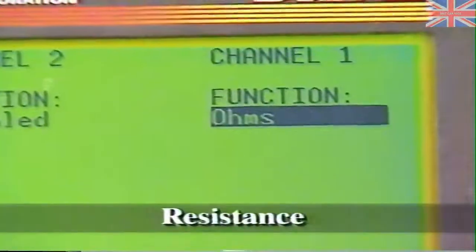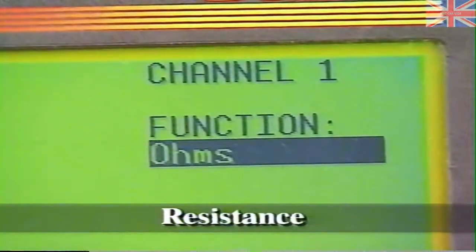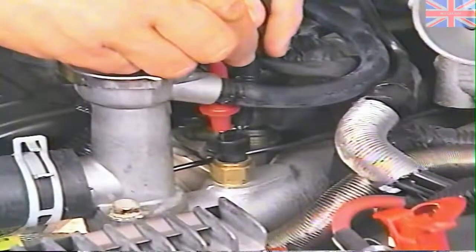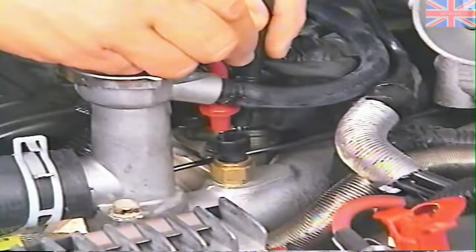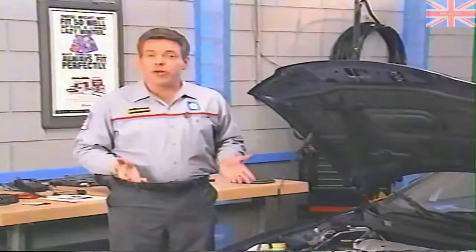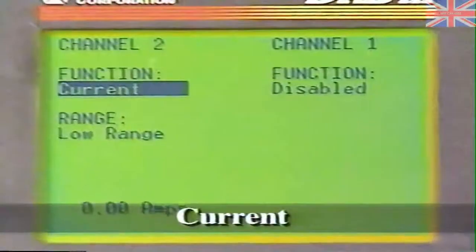Next on the list is ohms. The DRB3 ohm meter is capable of measuring resistance up to 1.12 mega ohms. To measure resistance, place the object between the test leads. Be sure the object being tested is not connected to voltage. Like voltage, the DRB3 resistance measurement is also auto-ranging, and you may hear a clicking from the unit due to this feature. Third is current.